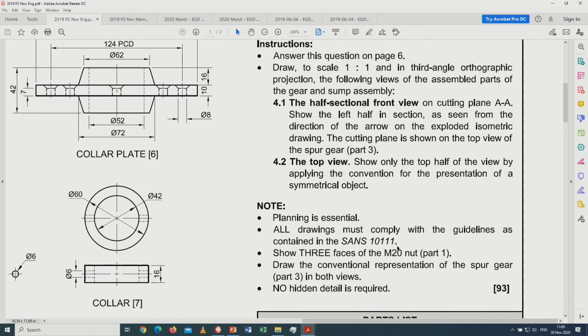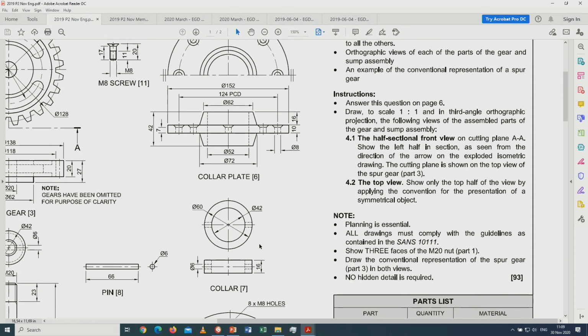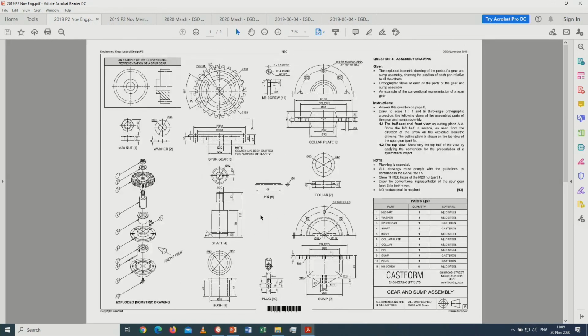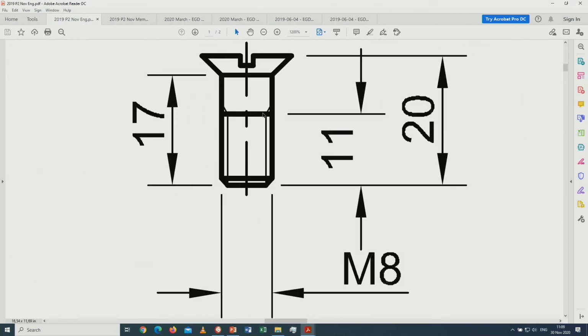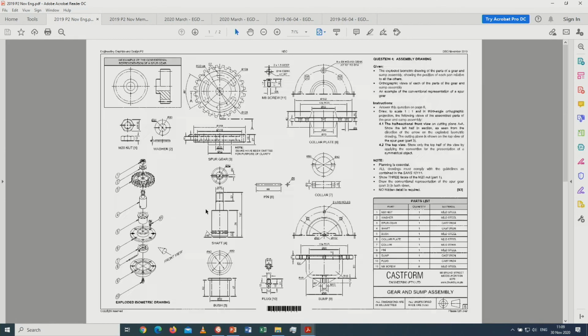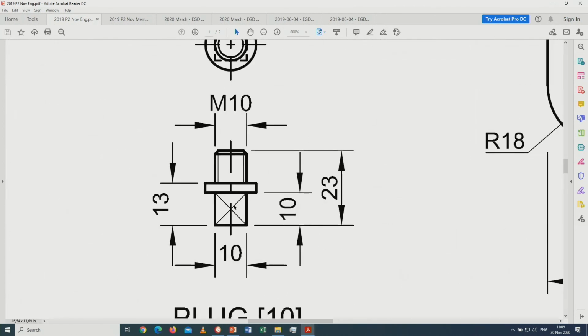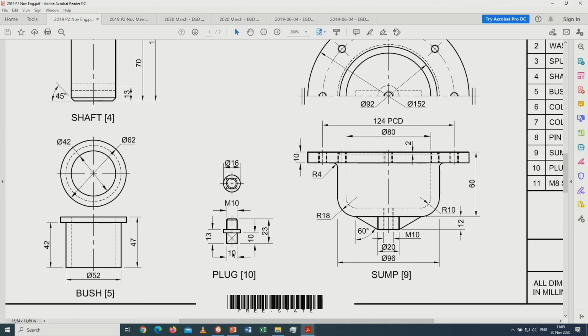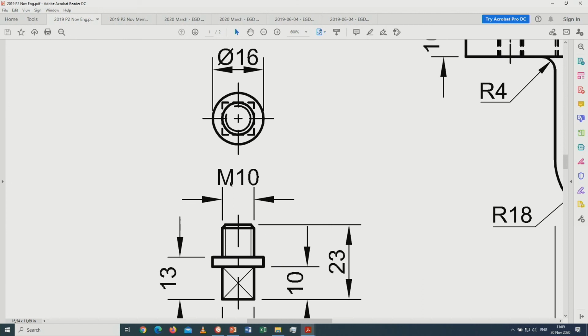Again, the work that I've done with mechanical analytical questions will be applicable over here. So how do I draw a square on the shaft? How do I draw a square thread? What is important about doing nuts and bolts, and what are those angles that I will find over there? And besides that, if it has got a square on the end like this one over here, it's been indicated but never said it's square, but I should have the knowledge that if it's corner to corner, it's a square and it's not round anymore. There's no diameter on the dimensions as well, although there are diameter dimensions on this upper part of it.